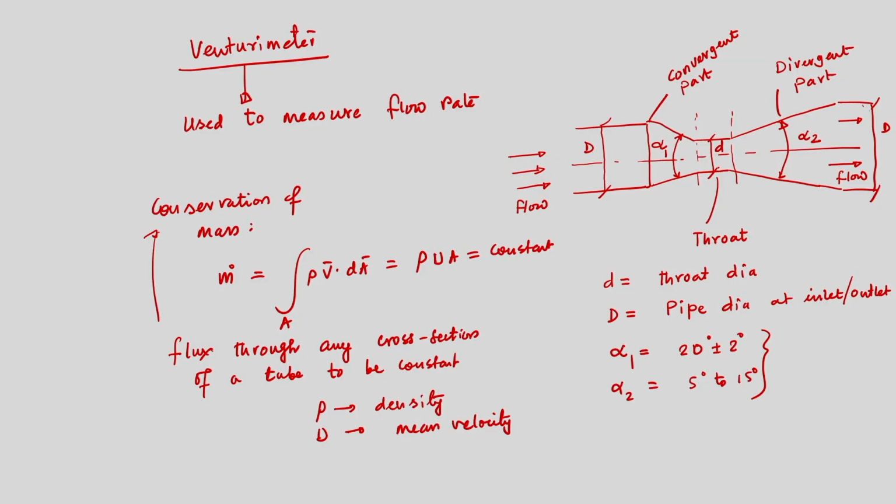Now, these aspects are also detailed in most undergraduate textbooks: when you are taking a pressure connection to measure the pressure from the throat, we need to ensure that the pressure tapping should be taken from those locations where the streamlines are perfectly parallel.